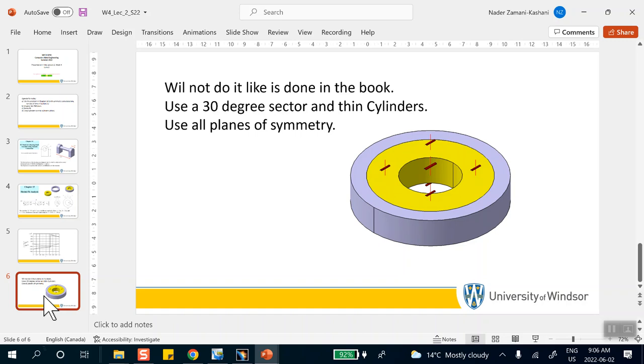Obviously, you can take a middle plane of symmetry, but what difference does it make? It's going to be exactly the same problem. It's just that the thickness has changed. The way it is right now, the top and the bottom, because I'm assuming it's a long tube, are roller. Okay, you want to take a plane of symmetry? No problem. Take it, and then you're going to put another roller there. So it's the same thing. But if I ask you to take a 30-degree sector, you can do that. 90-degree sector, etc. Be prepared for that. Anyway, any questions here? Move on.